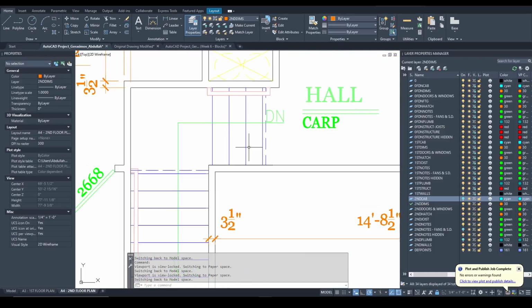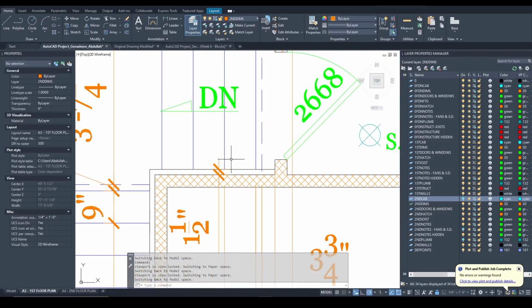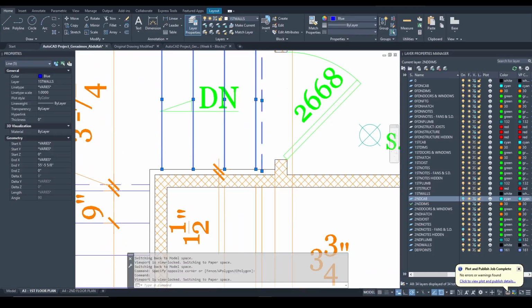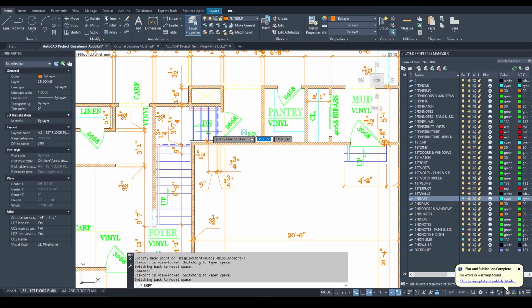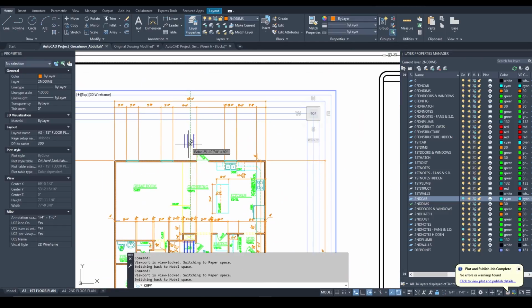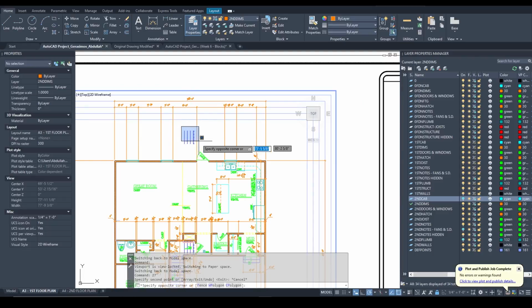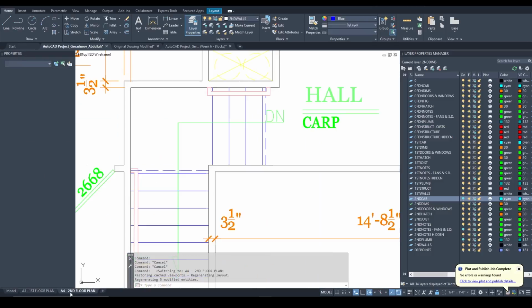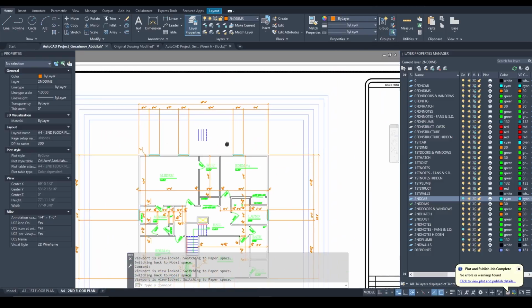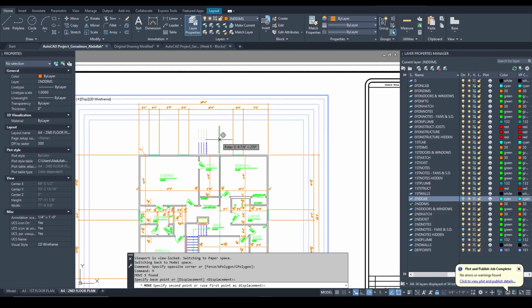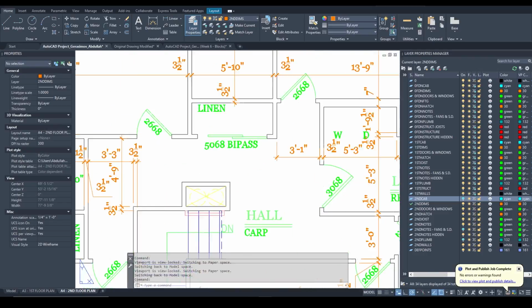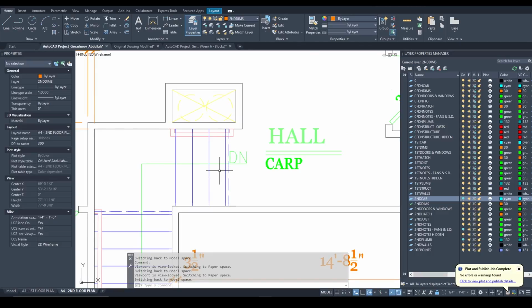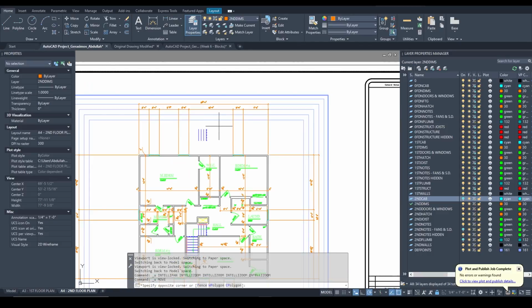Regarding these lines, these risers, they are a copy of these ones. So you can actually do the same thing, select them, copy them, in a place where you can easily get them. For instance, I would copy them somewhere here, and you can see 27 feet up, copy them, I select all of them, change the layer to the second walls, go to the A4 sheet, they're here, and I move them down exactly the same distance, 27 feet. And they line up perfectly with the ones that I have had before. So this is how you go about doing this.